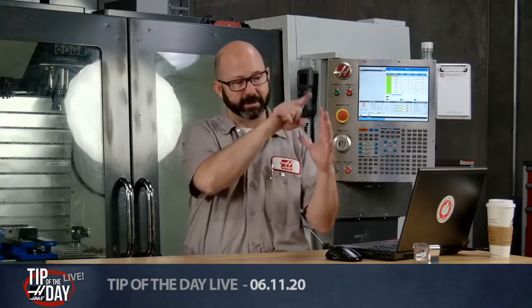On a HAAS machine, they've made it so amazingly easy. And we're definitely not going to change this. I hope we're not changing it ever. Because you program the part as if it's on the main spindle. Really easy. I've got all my programming here, tapping, turning, boring operations. I write the program for the main spindle. And then all I've got to do is put a G14 in front of that code, and it mirrors it all along the Z-axis, and it runs it on the sub spindle. Super easy. It just doesn't get any easier than that.